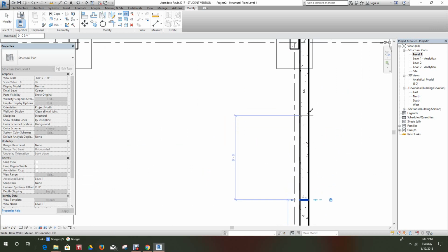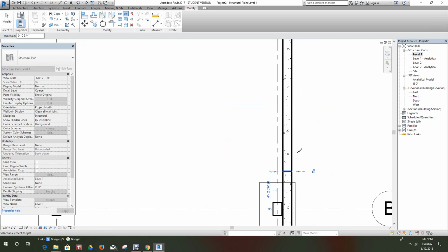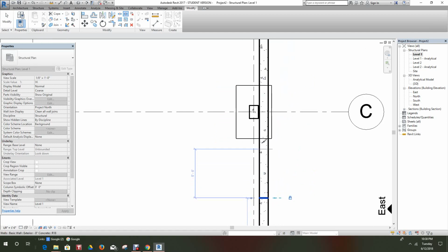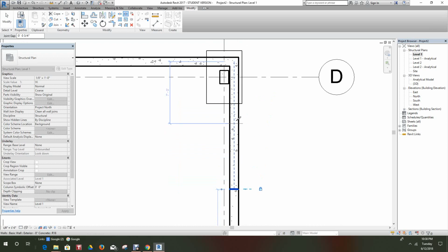So we're splitting at 3/4 inch gaps. And the main idea for the precast, they want to make as many panels the same as possible for production or prefabrication. So we go back with another 11. And we'll do another, we'll go 11 here, but they don't typically like to do it. They want to go right on the column, which I should have, but I don't have time for that. Getting late. And then we do another one here.